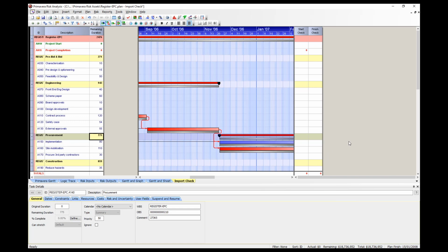This is just an example, but if this happens during import, you would need to go back into P6 and find out why these errors were caused in the first place. Then re-import your P6 schedule. It could be due to an incorrect calendar, incorrect hours per day, etc. But these errors must be corrected before re-importing.